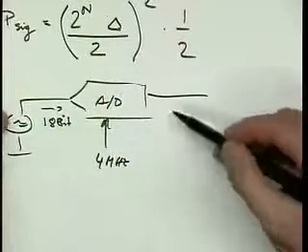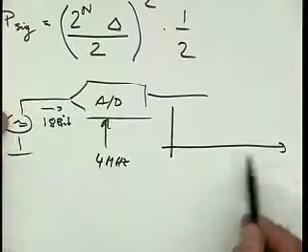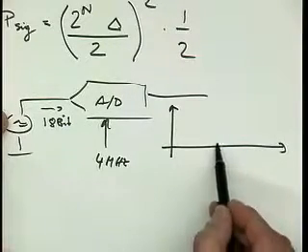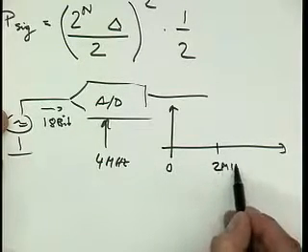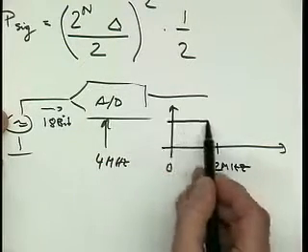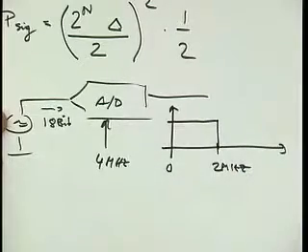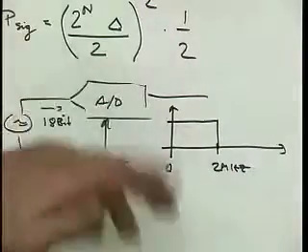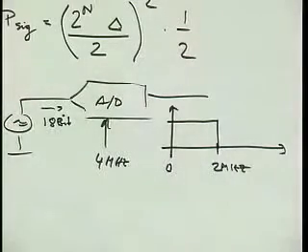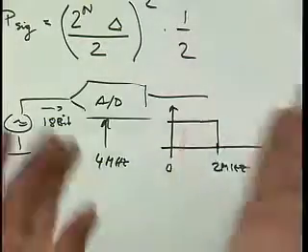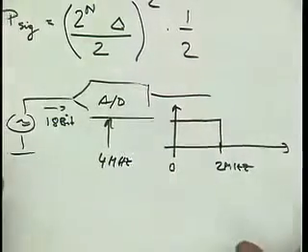Then out here comes thermal noise that goes from 0 to 2 megahertz. Now, we've argued before that the spectrum of this thermal noise is going to be approximately white, right? Let's assume that the A to D converter has many bits. We don't care, the quantization error is negligible. We are just concerned that despite all the good quantization, we still have thermal noise, and if it swamps out the LSB, then we still don't have our 20-bit A to D.